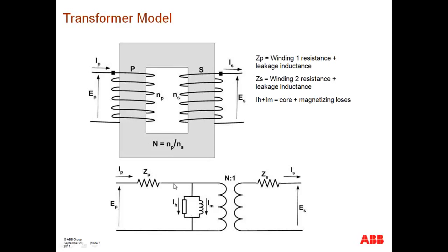If we assume the worst case scenario, to the left you're going to have a source, a source impedance, and the primary winding impedance, which again is the leakage inductance of the winding plus resistive losses of that winding. And let's say worst case scenario, you essentially have a short circuit between this point and this point. You're essentially short-circuiting the magnetizing branch. If you do that particular switch at voltage equals 0, then you're going to offset that current magnitude by square root of 2. So theoretically, your absolute worst case scenario cannot get any worse than that, because you're essentially completely disregarding the magnetizing branch of your transformer.